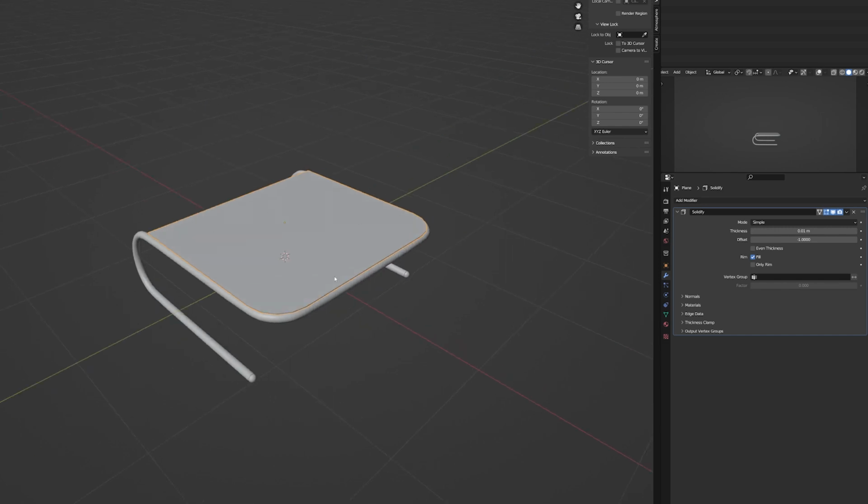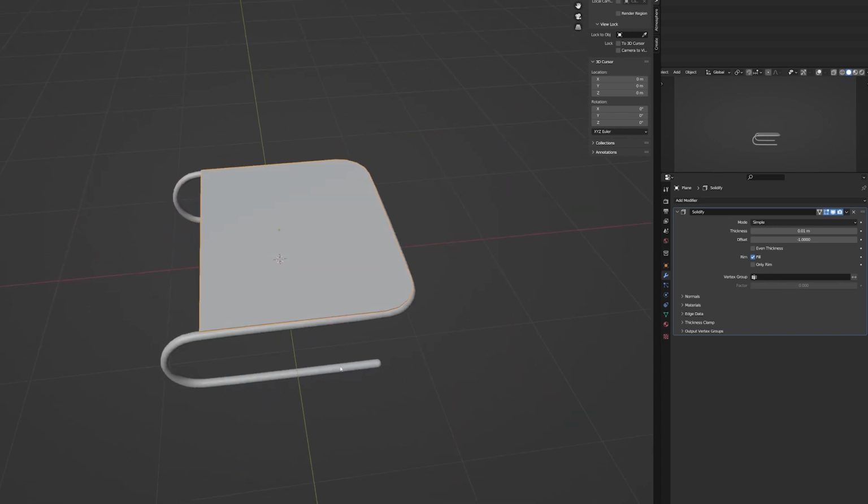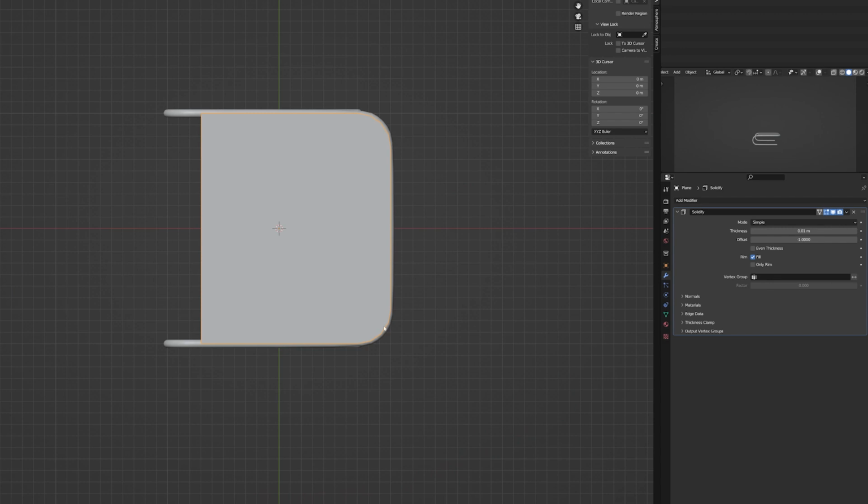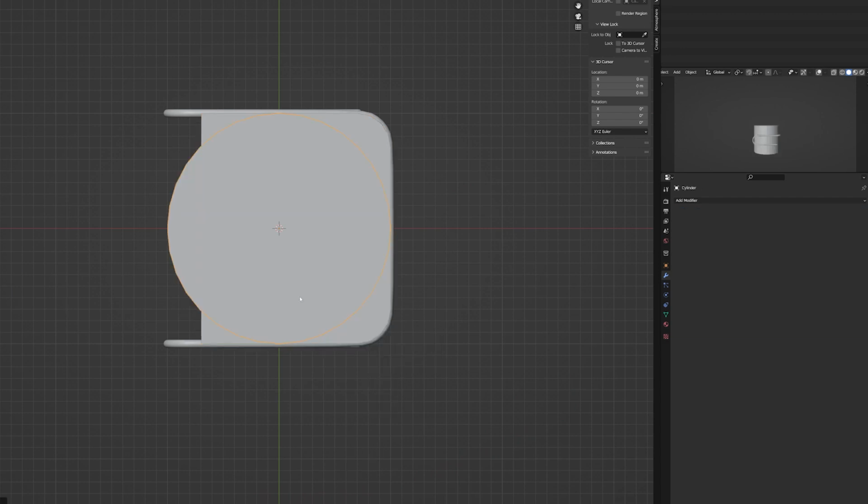All right, so for the last part of this plate, we can use a texture to add the holes in with an alpha mask or whatever, but let's try using a Boolean modifier. Let's try actually doing it with geometry. So I'm gonna go in the top view, hit 7 on the numpad, and create a cylinder. It has way too many faces. Let's bring 32 down to like 8, maybe 12.